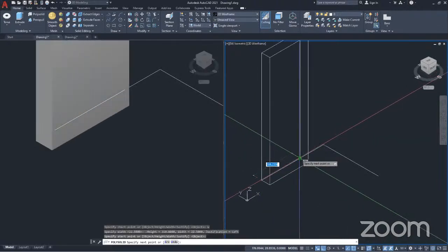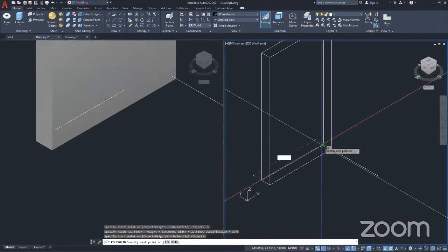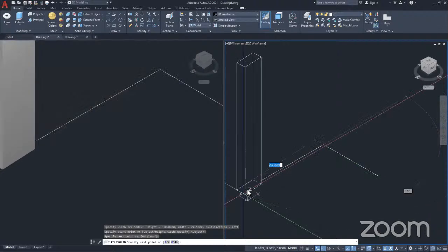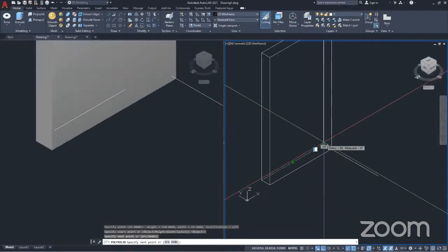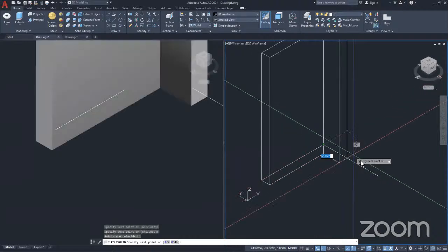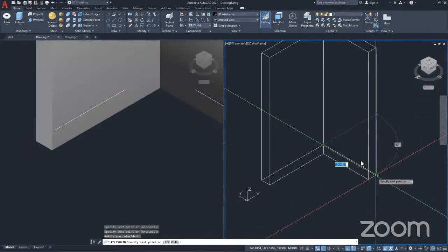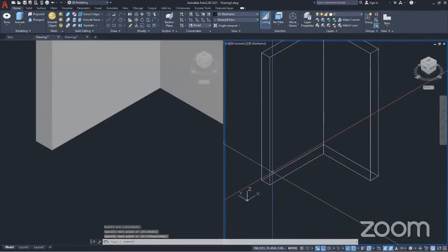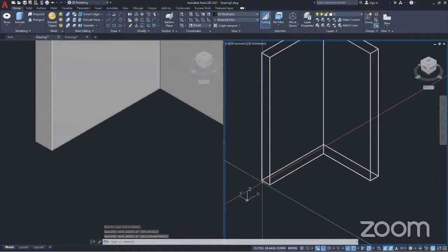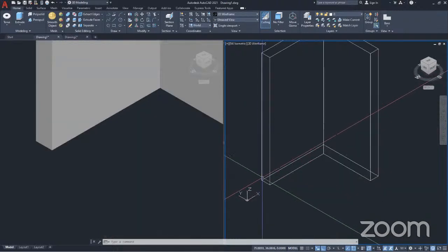I'm going to draw. You see, because I used the left option, now it started drawing. Oh, I did not click. Click to draw. Endpoint. And I'll leave it there. So now, you see, it started drawing from the left of the polysolid. It started drawing here. Did you understand?